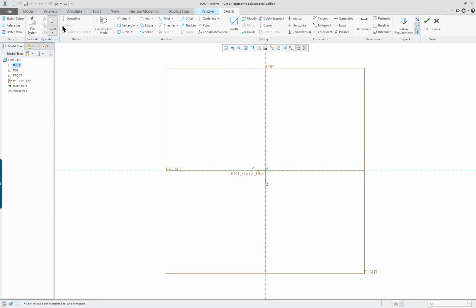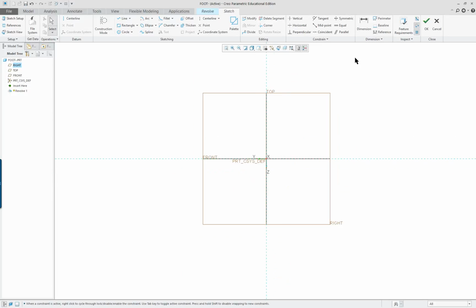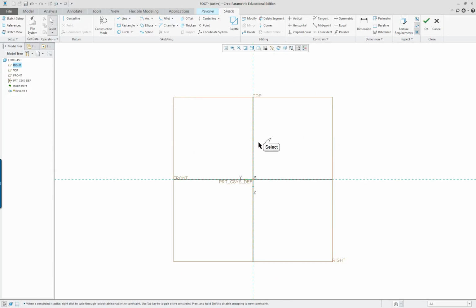There's only a few places that you need to do that with Creo or PTC products, and that's such as when you're doing the manufacturing or machining modules. So center line, I'm going to click 2 different spots. And if I put my cursor up here, it should come back. No, did I not get my center line? This should say line reference. And this should say center line. And I think I did not click on it correctly. So click on it once, click on it twice. There's something going on with my mouse. Middle mouse button. If I put my cursor here, it says axis of revolution.